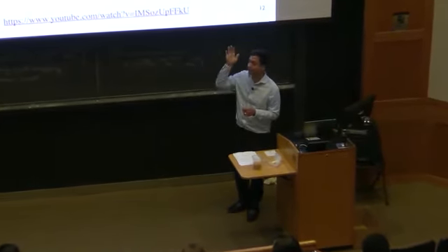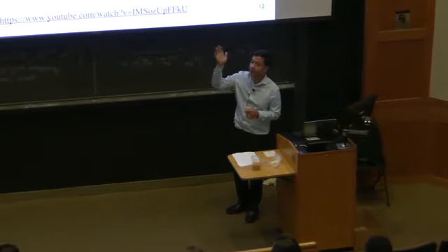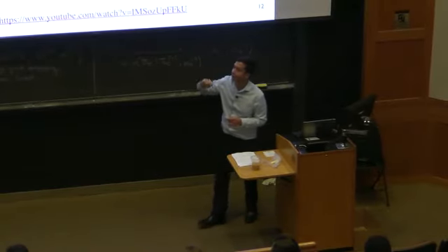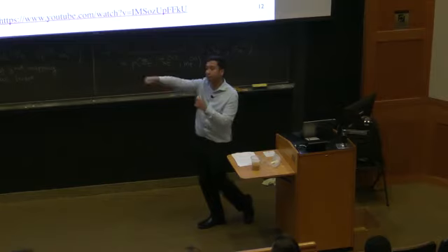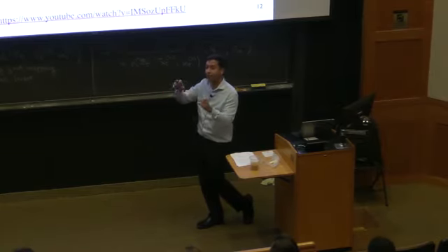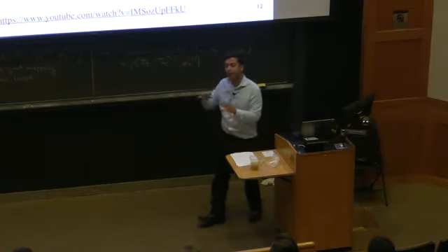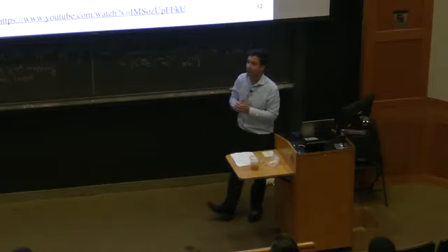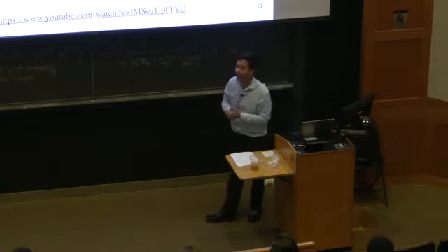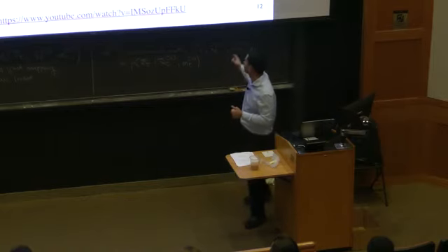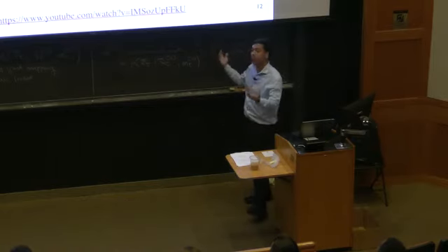One is the actual distance to an obstacle. The other is the probability that you miss an obstacle. The other one was the probability that you see a kind of obstacle that wasn't there. And then I think the fourth one was just some random noise. And then we concatenated those probabilities together. So that's one particular sensor model.